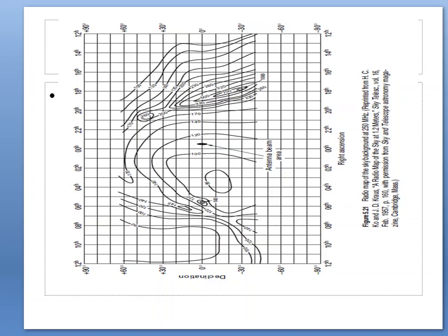And after that we moved to the sky noise temperature. In the sky noise temperature we analyzed the frequency with respect to noise temperature across different variations, starting from 10 to the power of minus 1 up to 10 to the power of 2 gigahertz range, and we estimated the noise temperature from 10 to the power of 0 to 10 to the power of 3.